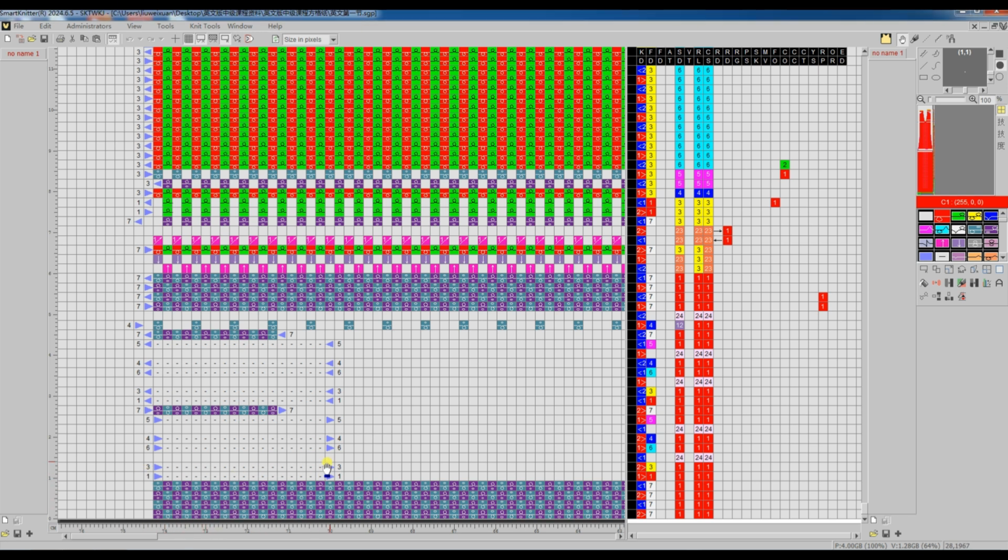Feeders 1, 3, 6, 4, 5 are brought in, using the Ravel yarn feeder 7 to secure the said feeders, then are brought outside the knitting area again. Feeder 4 is then carried to the right side for partial knitting of the shoulder and neckline later on.